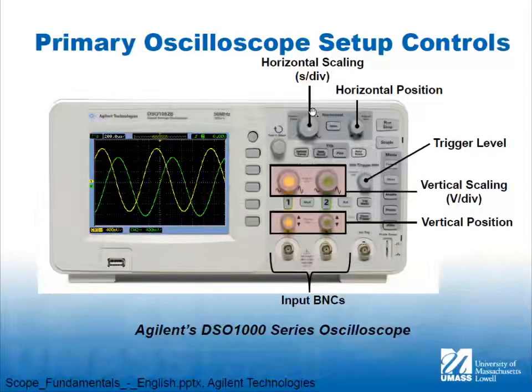Okay, the last useful thing is up here, and it's the horizontal scaling. So that's the resolution of the horizontal axis here. We saw that it was 1 microsecond. You turn it to the left, the number gets bigger. You turn it to the right, the number gets smaller, right? Because the resolution goes up when it's a smaller value, meaning the time base is going faster.